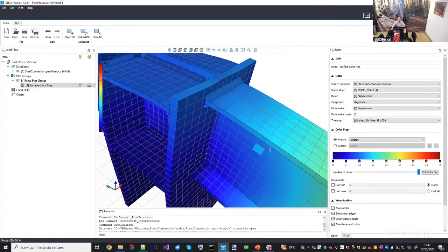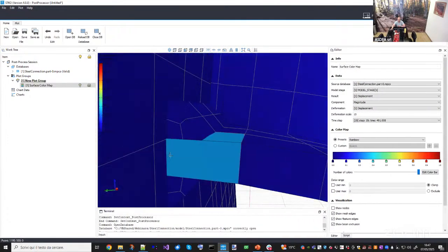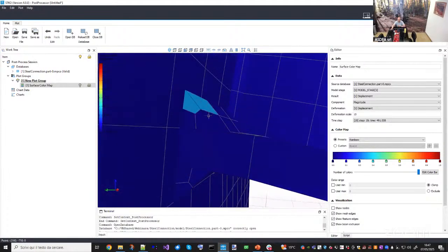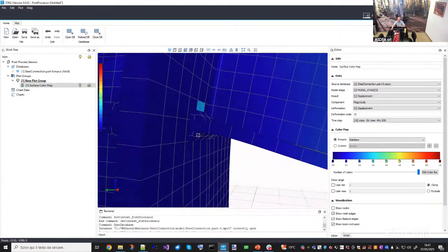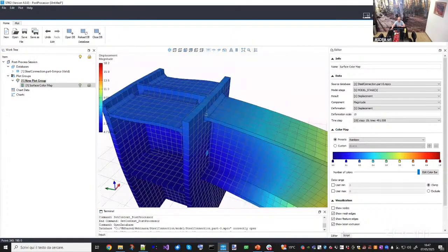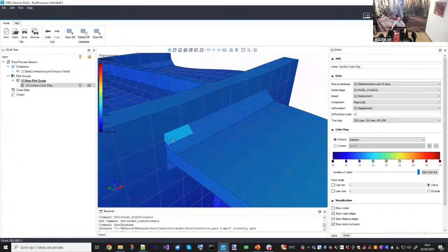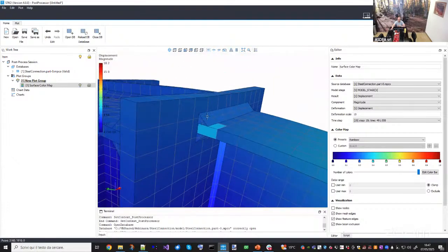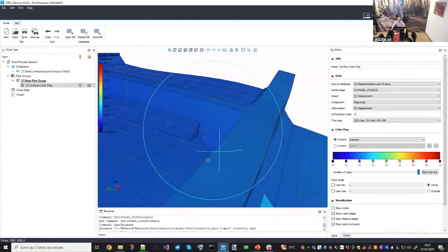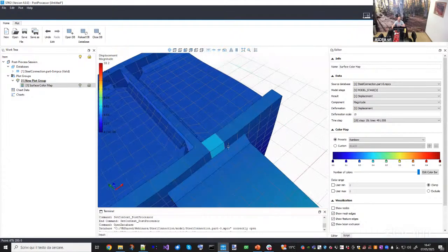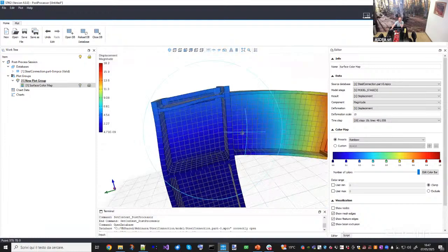Even if I'm not adding contact, there is no compenetration down here because now the welds are strong enough to transfer both tensile and compressive forces. As you can see, the embed element is working, attaching faces with incompatible meshes. So everything seems to work fine, okay?